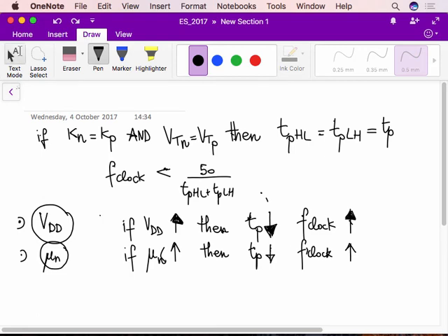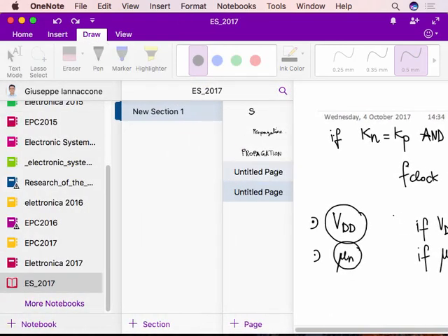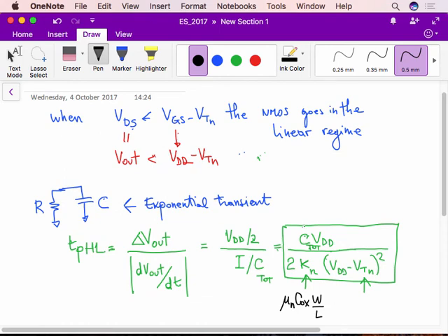There's an additional thing to look at here, which is the size. So this is interesting here. For example, the length of the transistor. Where does the length of the channel enter here? If you look here in the denominator, basically the length enters here, right? But the length enters also in the numerator, because if you look at the various components of C_tot, some of them are not dependent on the transistors.